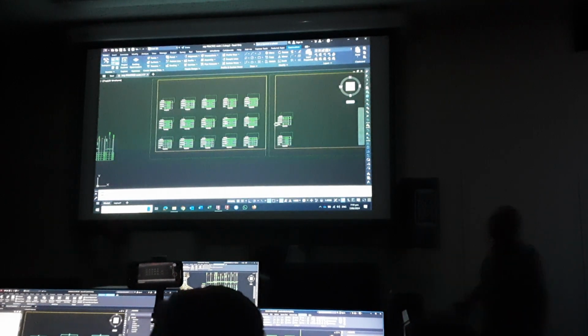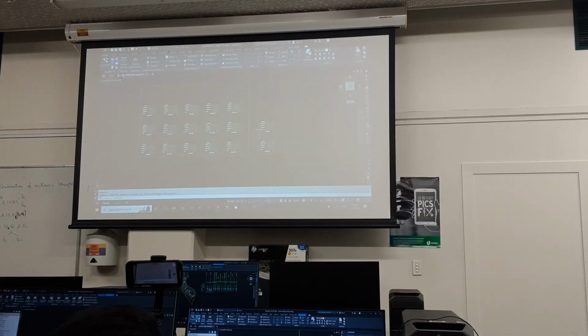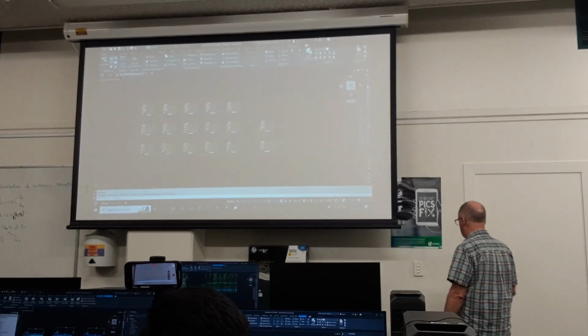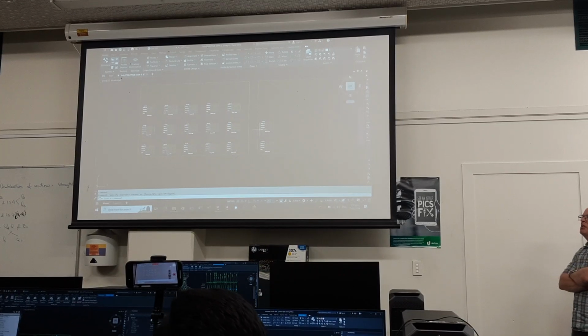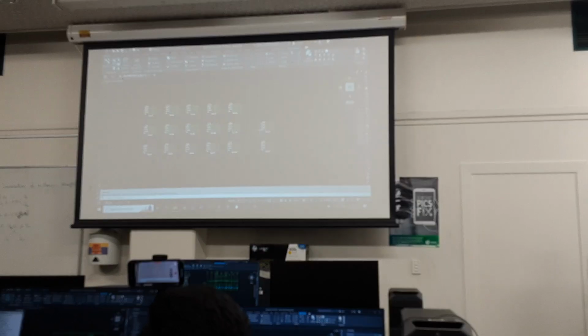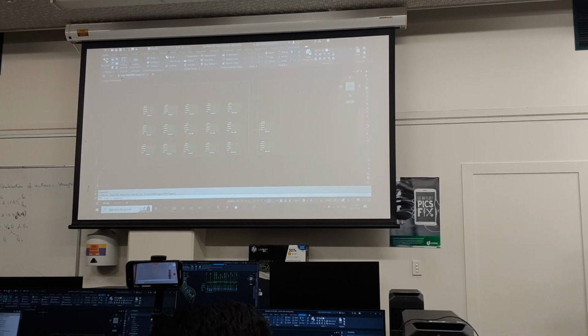There are 2 sheets here, and it's pretty much saying what's going to fit in AutoCAD in terms of the scale that we've asked for. Usually what I would do there, we've got 1, 2, 3, 4, 5 times 3, 15, 17, call that 18, probably 9 per sheet would be about right, just to even it out a little bit, 9 and 8, something like that.